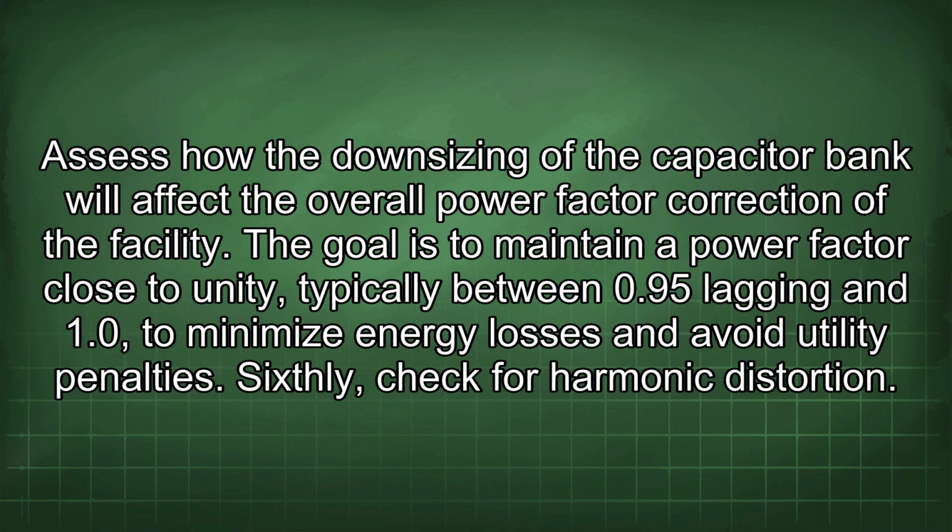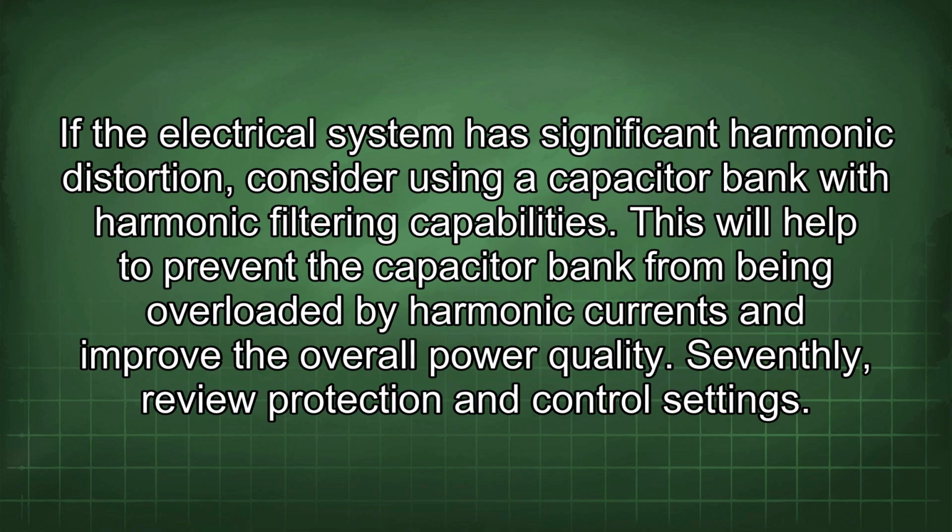Sixthly, check for harmonic distortion. If the electrical system has significant harmonic distortion, consider using a capacitor bank with harmonic filtering capabilities. This will help to prevent the capacitor bank from being overloaded by harmonic currents and improve the overall power quality.